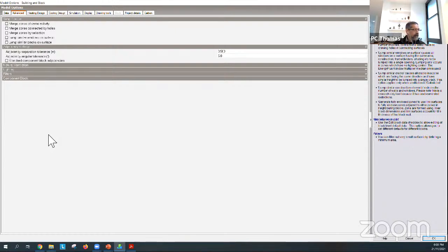Why that was done was that when computers were expensive, EnergyPlus gave you an option where if you had exactly the same size of window on a wall, it would model only one window, then it would multiply by the number of windows. That's perfectly fine for energy, not fine for natural ventilation. It's also not fine for energy if you have shading on the building where only part of that wall is shaded. So we really shouldn't be doing this at all. So these two things you must do.